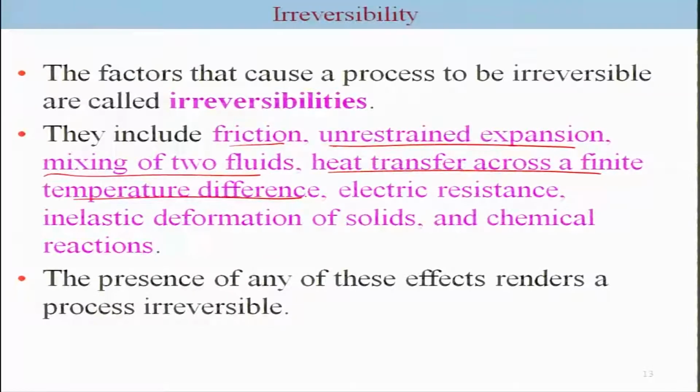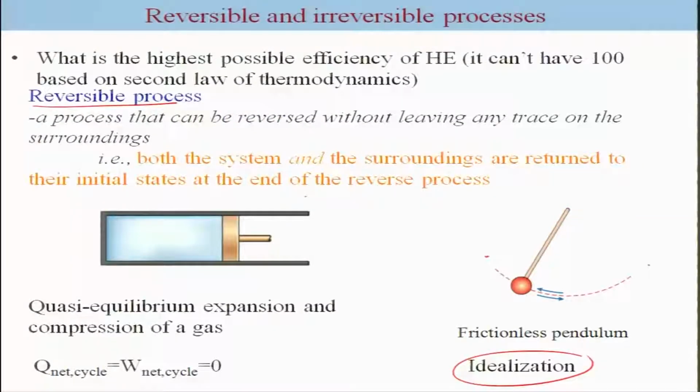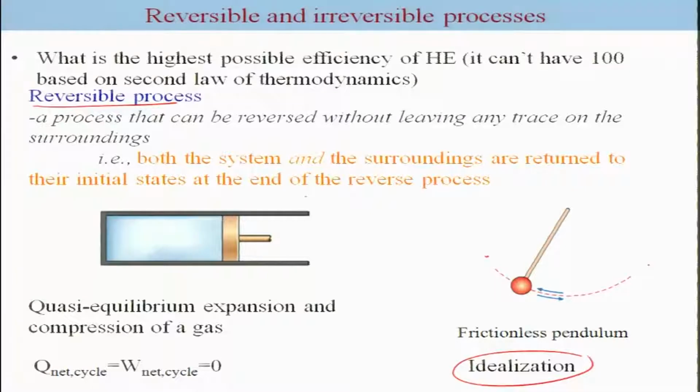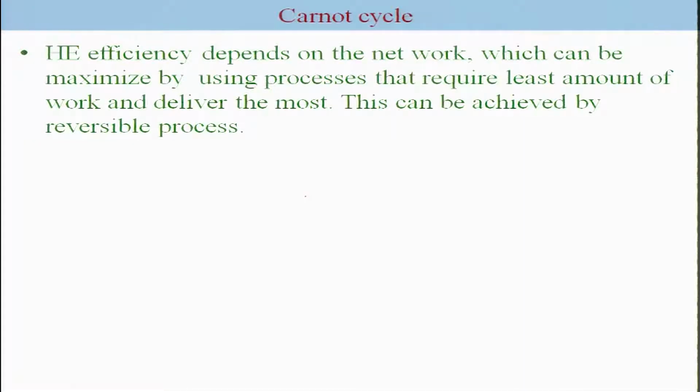Besides this, the one which we have talked about is basically a totally reversible process. In addition, we also consider when the system is internally reversible. In such a case, we assume that the system can be brought to the original state, however, the surrounding may contain all the irreversibilities. So, in those kinds of cases we call it internally reversible, where from the system to the surrounding there may be a finite temperature difference, but within the system we consider that everything is reversible. Those cases, particularly internally reversible, are the ones which we are going to consider most of the time when we discuss problems.